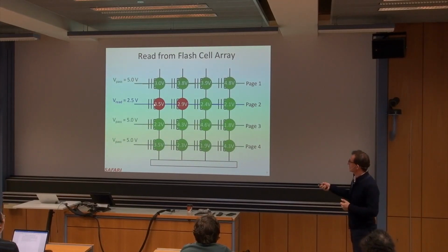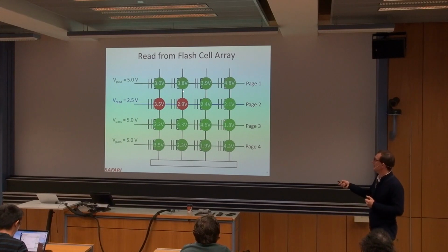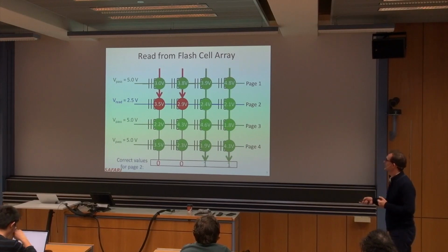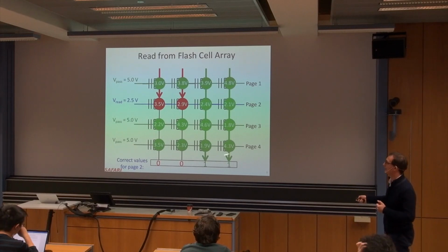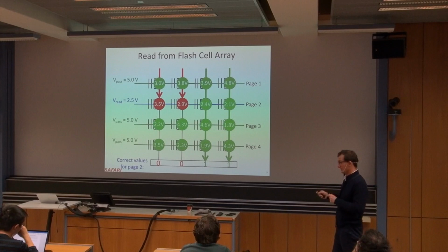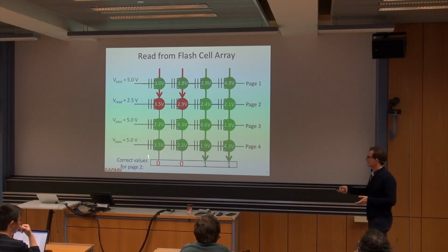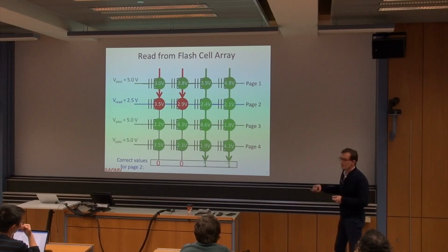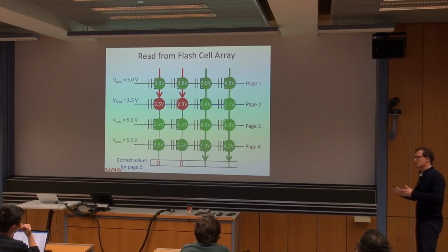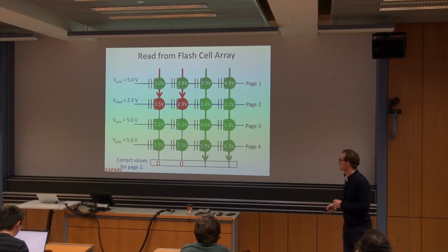And when we do that, these two transistors are inhibited because their threshold voltages are higher than the read reference voltage, so they don't pass through what they have, so you get a 0 at the end, whereas here they pass through what they have, so you get a 1. And these don't interfere because they're always turned off, if you will, right? Because the pass-through voltage, at least the voltage that you apply to the gate, is always higher than the values that you see on these pages that you're not reading. As a result, in the sense amplifiers, you get 0, 0, 1, 1, which is really what you want by reading that page. Of course, there's a sense amplification process over here also, which we're not going to talk about.